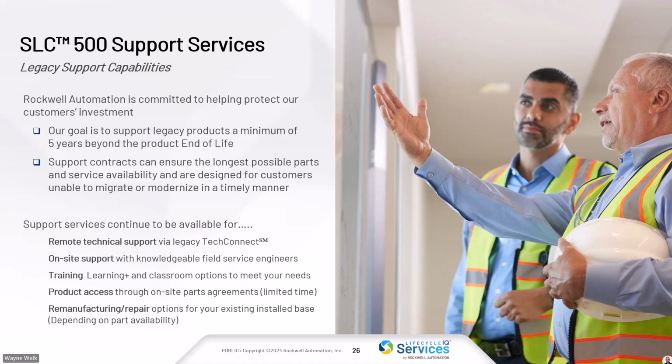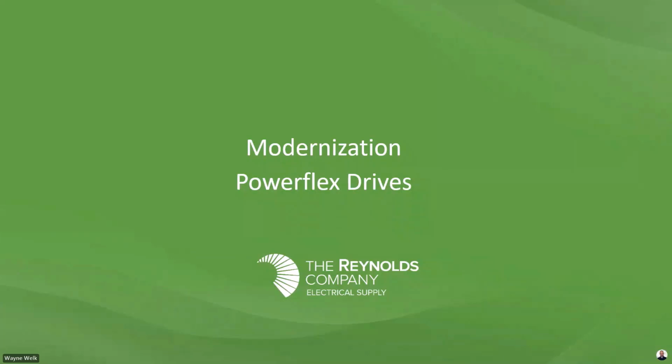So as you are trying to phase yourself out of relying on hardware that you can't buy new anymore, we can keep using that repair loop to keep things going, especially if, say, half of your machines have converted. We can use the SLC 500s from those machines as spares towards the remaining ones. That helps you figure out a 5-year plan for modernization instead of needing to find capital to do everything at once within a year. And so with that, I will step aside.